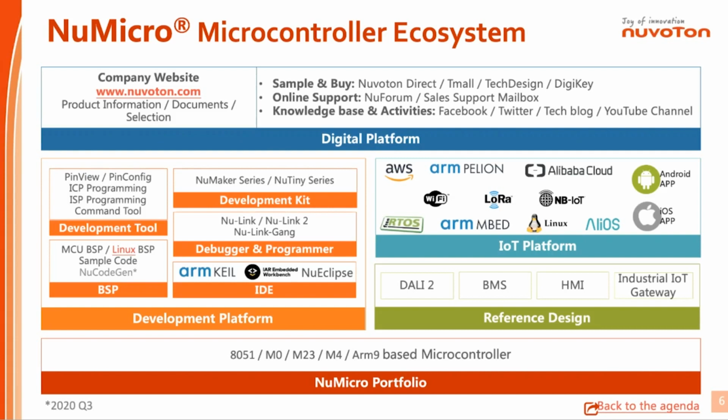In addition to the hardware debugger, Nuvoton also supports software tools like Pin Config for easy multifunction pin setting to generate a code template and ORCAD file, and a Pin View for the integrated IDE tools to show the pin status in real time. It's especially useful for pin setting and leakage current debugging.